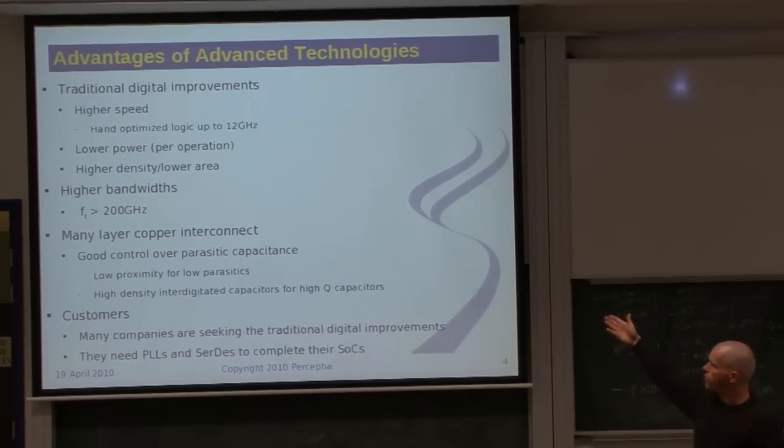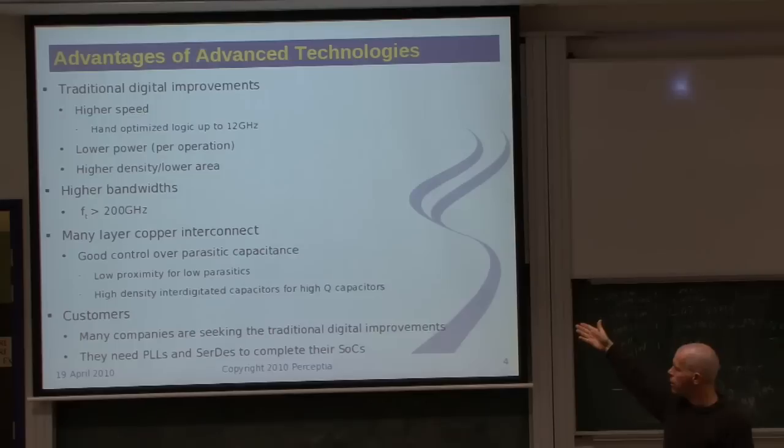We've reduced our parasitic capacitance, so our power goes down, and we've got higher density of gates, so we can fit more in a lower area. We've got lots of layers of copper. This process had 11 layers of copper. If you go talk to university mates who use the cheap processes that'll do a good deal for a university, they might have 3 layers of metal, which really makes hooking things up difficult. And we're going there because that's where our customers are. This is business after all.